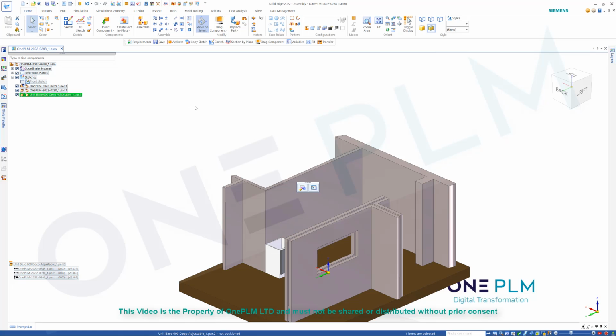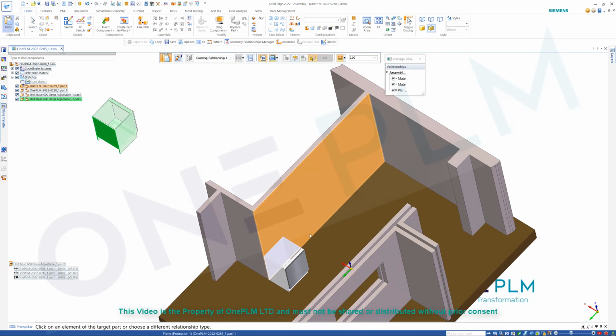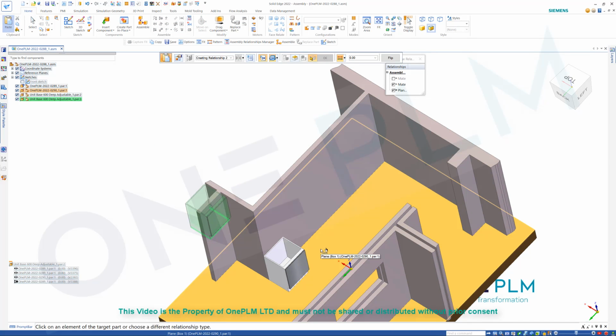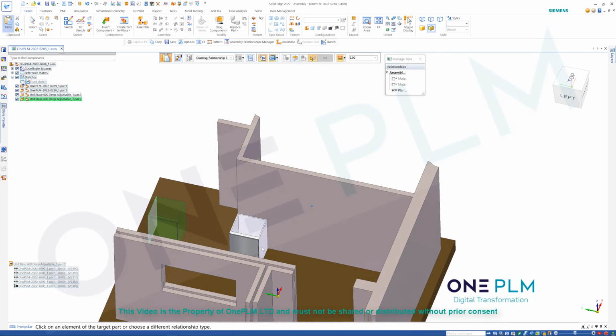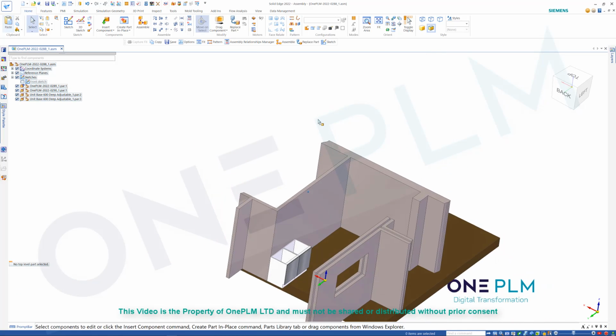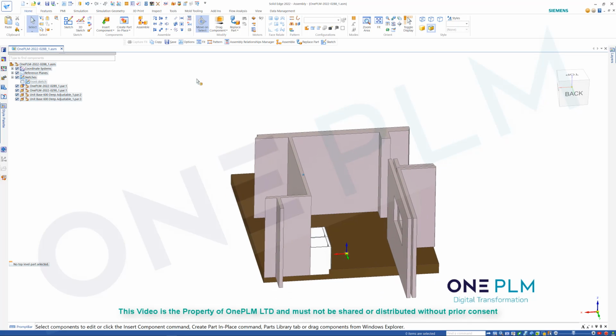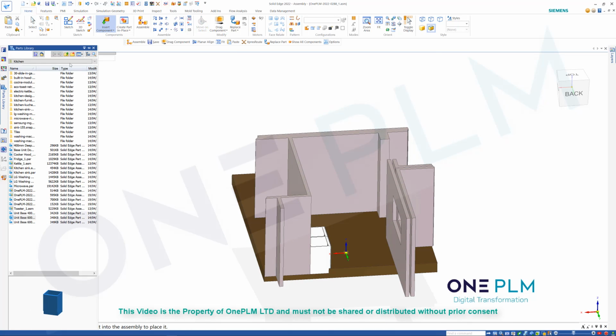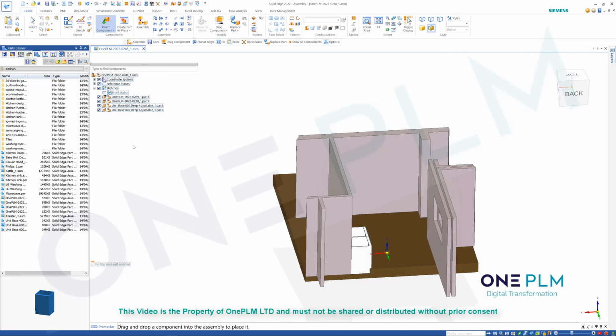And if I do copy and paste, it's just a matter now of pasting that back in and specifying where that needs to go. We could possibly pattern it, but quite often we're not going to end up doing that many different units on there. What I'm going to do is, on my insert components, pin it, this little pin icon on here. I'm going to click on that.